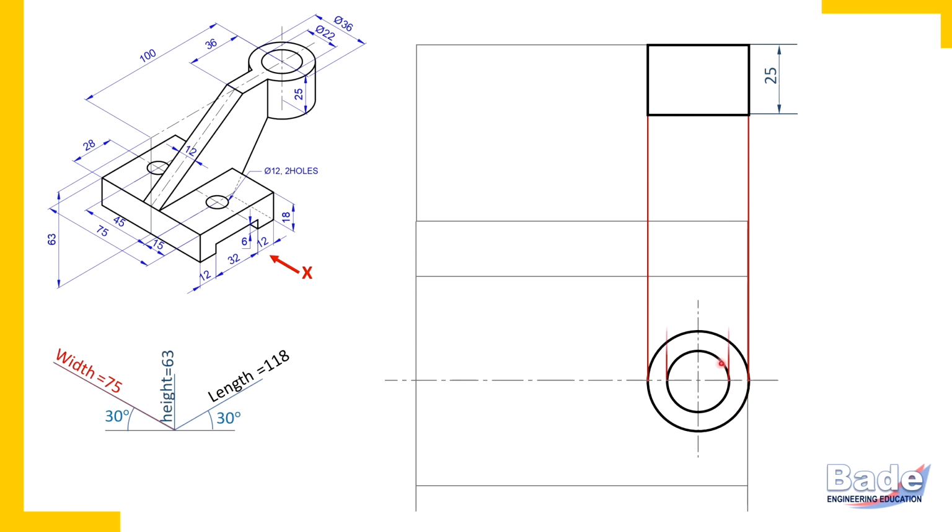And the hole, project its horizontal dimension, and it is a through hole from the top to the bottom of the cylinder. Draw dotted lines. So where is this hole in the front view? Remember, the hole has an edge at the top, that circular edge, and this edge appears horizontal and it coincides with the edge of the cylinder. So this rectangle is a dotted rectangle and that is the hole in the front view. Now when a cylinder appears as a rectangle in a view, then you should draw its axis. So we have drawn the axis of the cylinder or axis of the cylindrical hole.